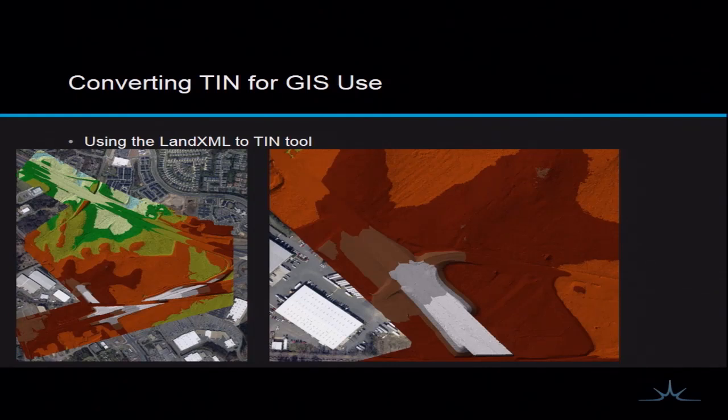So what we end up having to do is we get all these different TIN files, but for our work, when we digitize lines and we use the Interpolate Shape tool in 3D, if any vertex on that line falls outside of the TIN that you're using to 3D the line, the whole line doesn't get 3D'd at all. So we like to combine all the TIN files we get from the engineers into one.